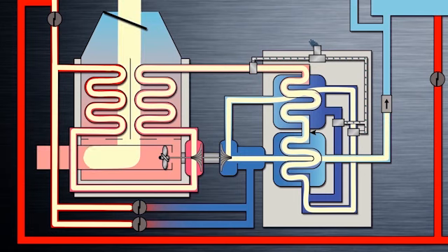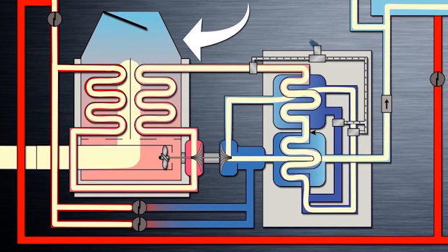It's important to keep air free from moisture to minimize the risk of icing at low temperatures. All the collected water from the air conditioning pack water extractors is ducted and sprayed into the ram air inlet so that by evaporation, the ram air stream becomes cooler and therefore more efficient in the heat exchange process.